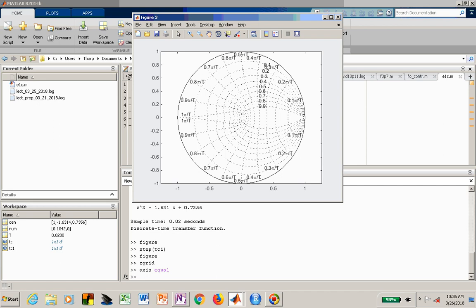Now we have a circle, and the logarithmic spirals, which are these heart shapes that I was suggesting before, are labeled 0.9 for the first one you see closest to the origin, and then they decrease in zeta value up to 0.1, and then the unit circle is a zeta value of 0. And these other lines are perpendicular to these logarithmic spirals, and those correspond to the frequency, and when they're on the unit circle, those are the natural frequency.